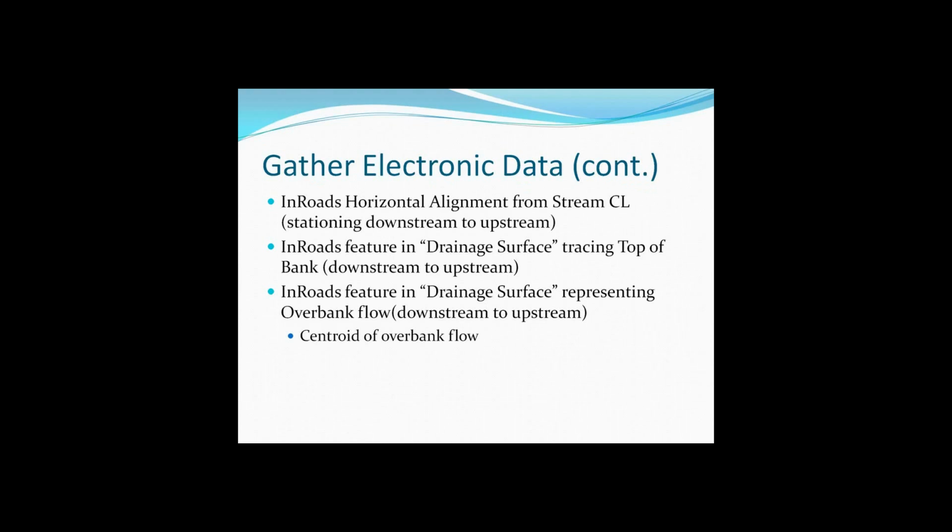And I just wanted to mention what these actually do so that you don't get too freaked out about making sure that they're extremely precise. The center line gives you the river station that the cross-section's at, and it gives you the downstream reach length for the channel in HEC RAS. The top of bank, the only thing it does is set laterally the location of the bank.